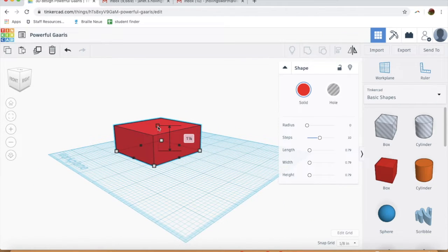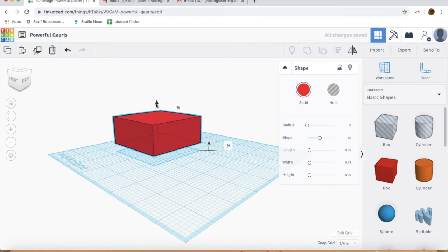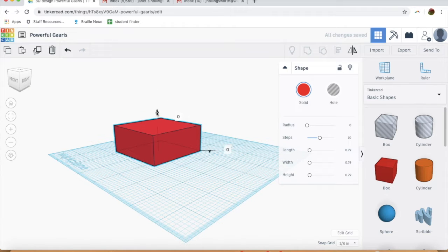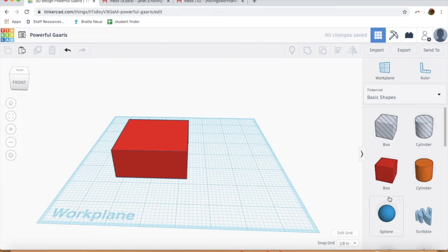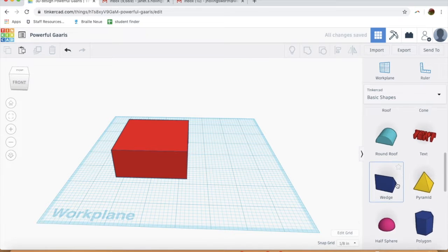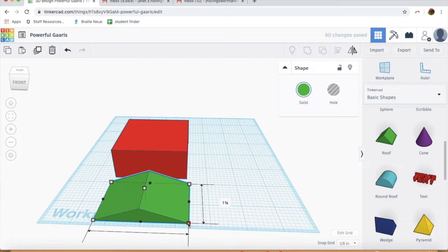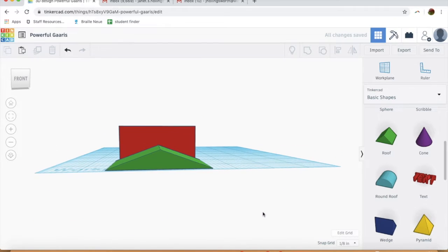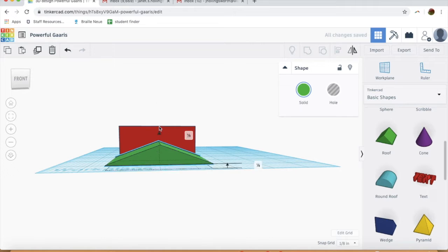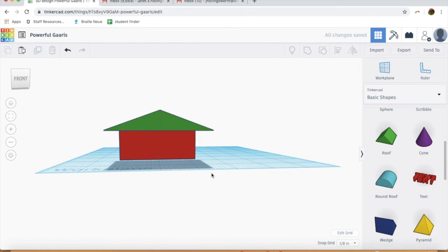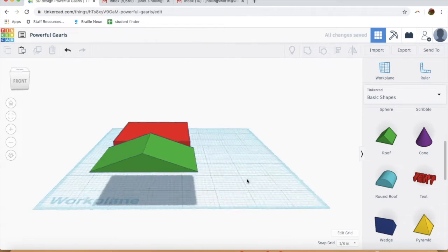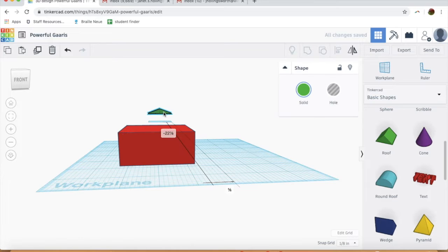Orbiting is important. That's going to be using your mouse and the right clicker. Moving up and down in space is using this arrow up top or the command or control button with your arrow pad on the keypad. Bring in other objects, manipulate them, move them around, orbit, and orbit often, because sometimes you can get into a situation where things look like they are a certain way, but they're actually not. And then you go to move it, and you can get lost in space.